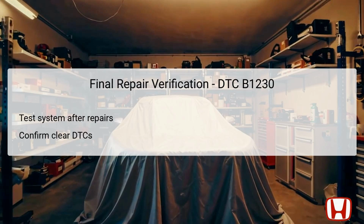After completing the troubleshooting steps and making any necessary repairs, it is pivotal to conduct a final verification test to ensure proper operation of the climate control system. This involves turning on the vehicle and verifying that the sunlight sensor and other related systems are functioning as intended. Technicians should utilize the HDS to check if any DTCs persist.